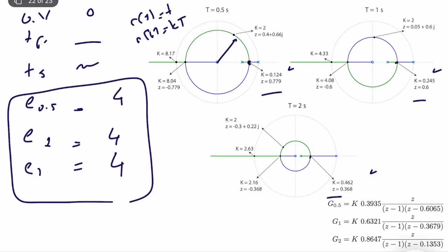So can you say that changing sampling time doesn't change anything? It's not, because as you can see, error statistic is 4. So in terms of percentages, now we cannot really measure percentages. It's a large number. It's not acceptable. So if you need to also improve the statistical performance, then you technically have to move away from this point, and as soon as you become oscillatory, you start losing performance when you increase sampling time.